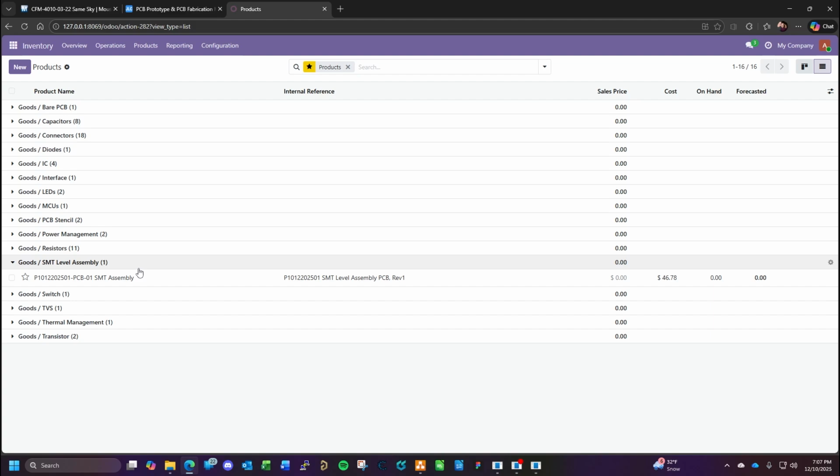Technically, that's the proper way to do things. If you have things that are sub-assemblies or would require additional manufacturing process, that's what you would want to do. Is actually have them as separate BOM items, as separate inventory items. That way you can track all of your labor, all your material usage more properly, your workstation effectiveness. Or if you decided to outsource and have that fan assembly made by somebody else, a company that specializes in that, you'd want to track all that. You would definitely probably have a separate part number for it. So we'll go from there.